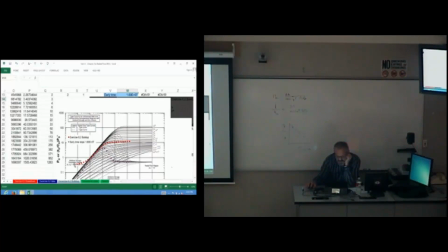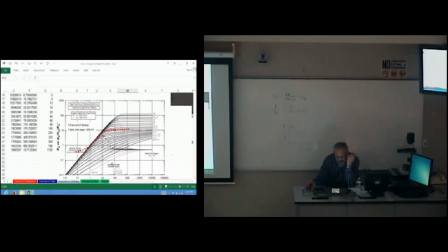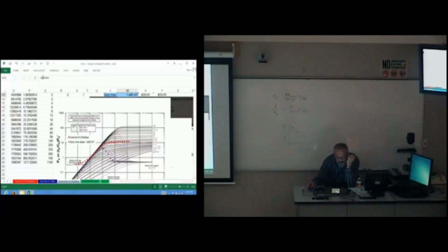And I've never seen this tail up on an actual buildup before. Of course, not saying I did it right, but on this same problem, it comes down and tails up exactly like that, and I couldn't get rid of it. I'm not quite sure what is wrong with the data, but the derivative data gives me pretty good unit slopes. Both the derivative and pressure should be unit slope. My derivative looks almost exactly like that, but I got that tail also. Yeah, me too.